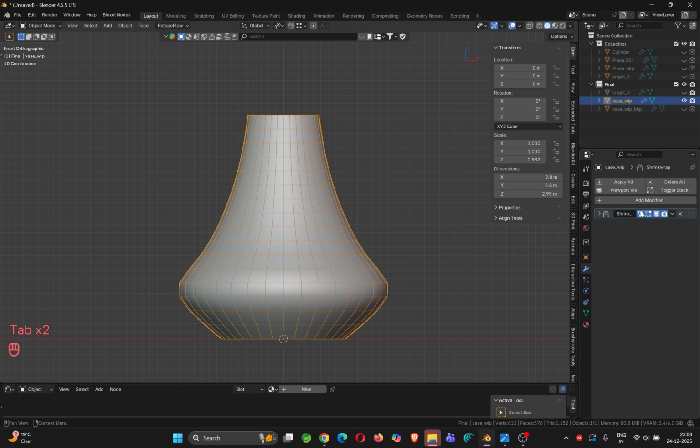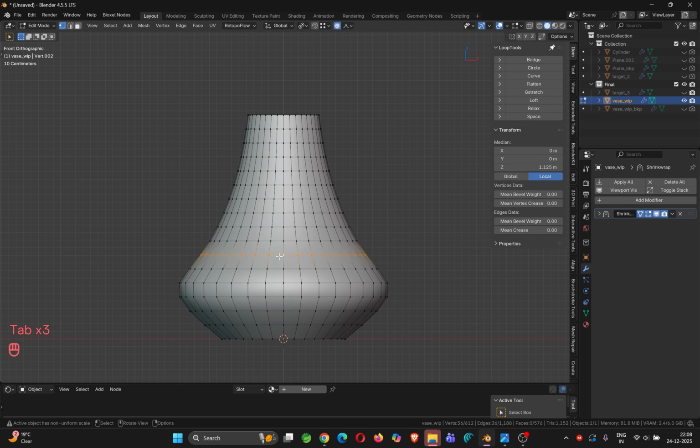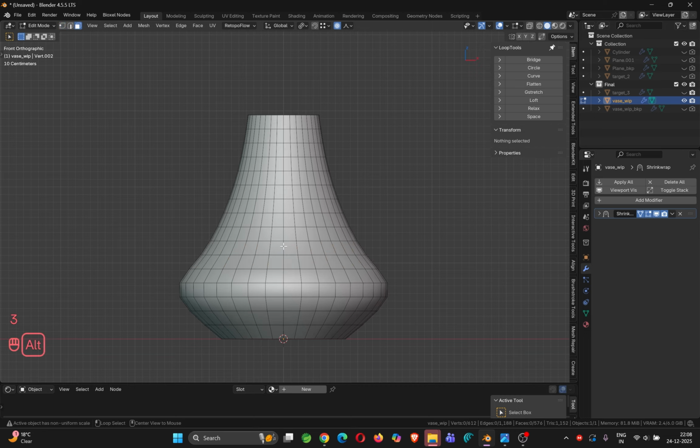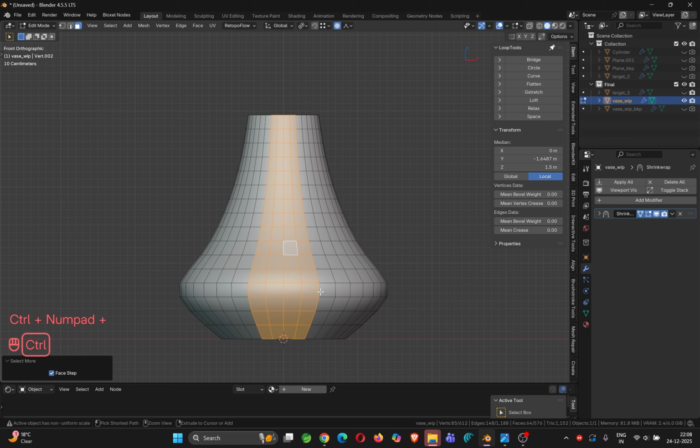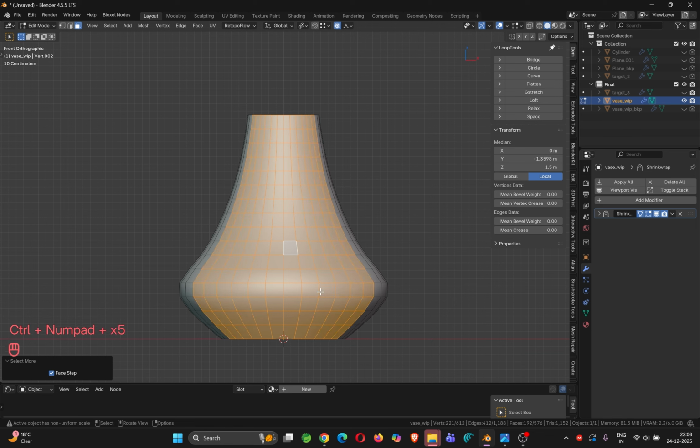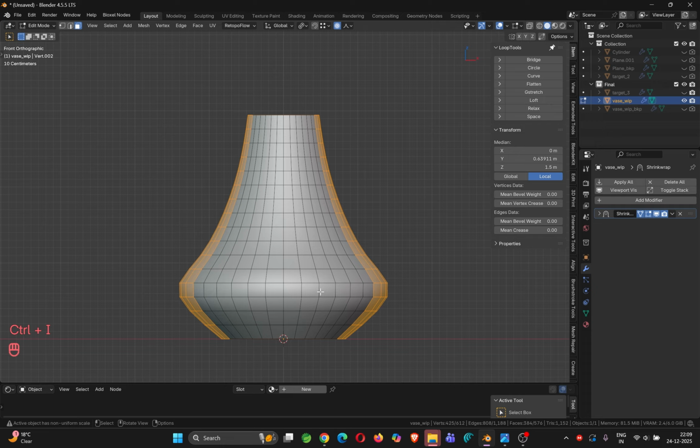Now let me also enable the edit mode. Now see, I am getting 36 vertices, so that means I will also be having 36 faces. So if I want to make 3 details radially symmetric, I need to select 12 faces on each side. So I will just select these 2 strips and use Ctrl plus to select 4, 6, 8, 10, 12. Okay, and the rest of the items I can safely delete.